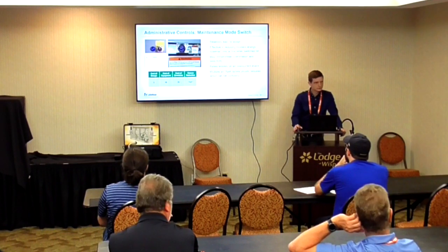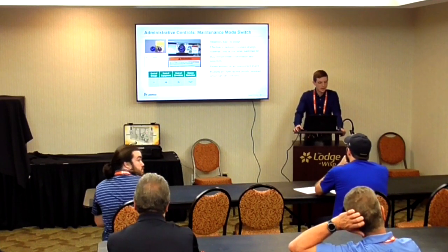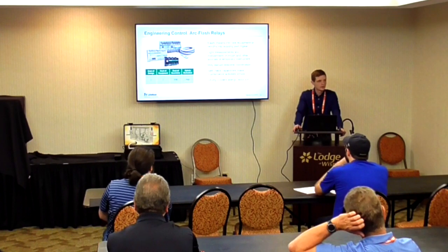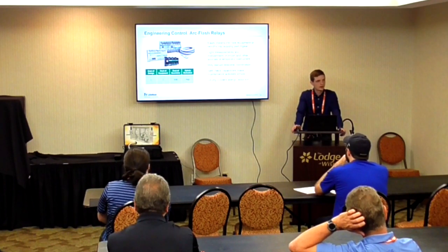How many milliseconds does this clear the breaker? So the relay itself is 1 millisecond. The rest of the time is dependent on your breaker, so the condition of your breaker, speed of your breaker. And that's typically about 35 to 60 milliseconds.